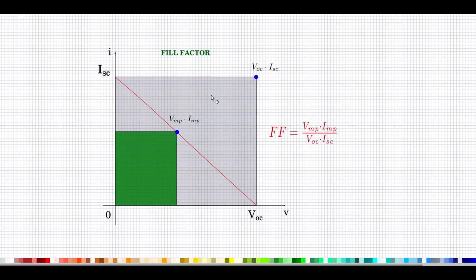So if you take our typical PV cell, it will be much better than this straight line. It will have a curved line like this. So this practical PV cell characteristic would have a peak power area as shown in blue here, much larger than this green area as shown here, as encompassed by the peak power point of the bad cell. So apparently, just looking at this, you see that a PV cell having this curve is much better than this because this area is greater than this.